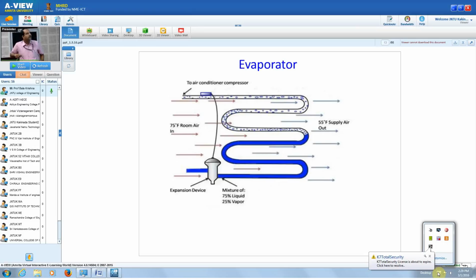Next slide. So this is also the same evaporator. See, this is the expansion device. The refrigerant is coming from the condenser. Then here the blue line, some liquid, slowly will be converted into gas. Then this is the sensor, the same as you have seen previously in this type of figure. This sends the outlet temperature of the evaporator, after taking the heat from the products.